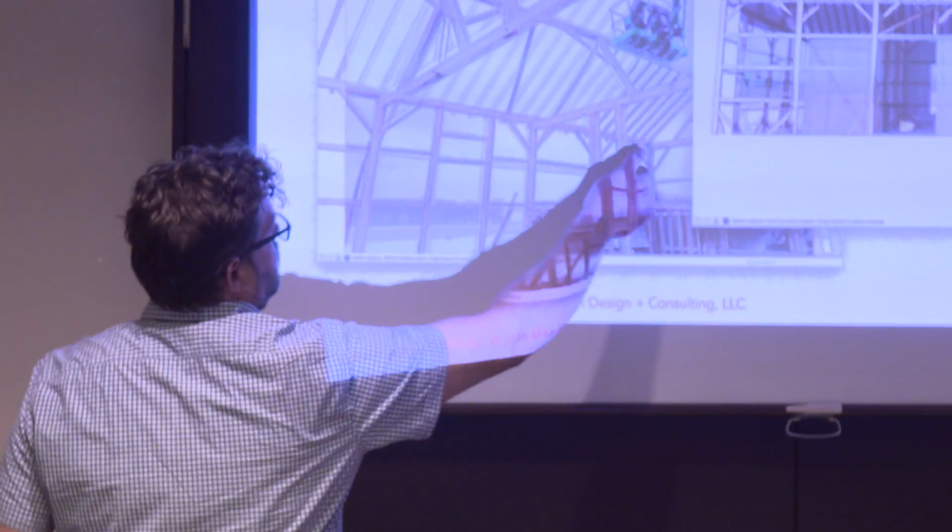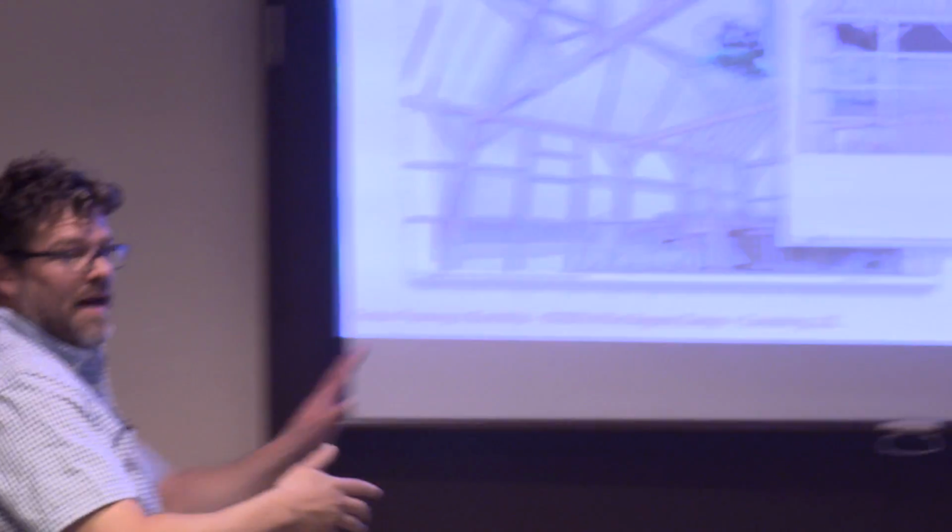Now, in the barn, this is easier for the stuff that doesn't need to be exact. If he had said, I want you to add this onto my house, I'd have gone through the trouble. I'd have gotten some really good photos of his house and done a photo match and then plunked the thing on after I did some hard work. But in this one, this actually was a photo match, and I matched the inside corner here and here and here. I matched that photo, and then when I started to build the timbers, I used that geometry as the guide for it. So it really depends on what you're trying to do.